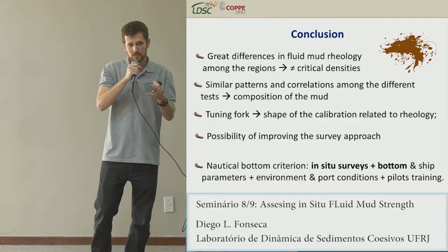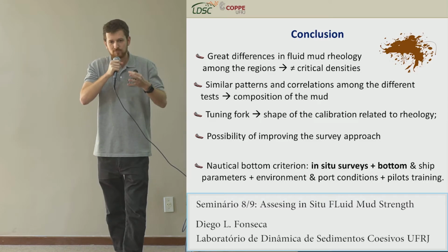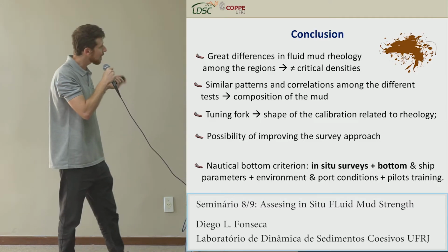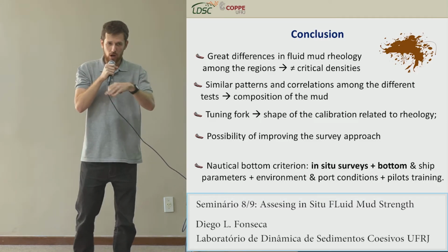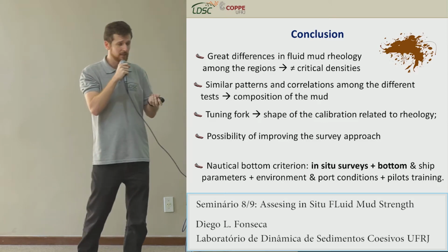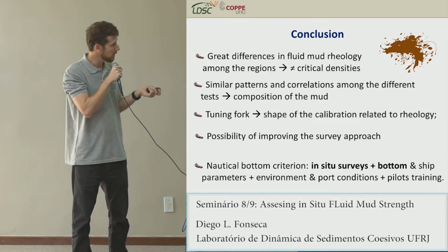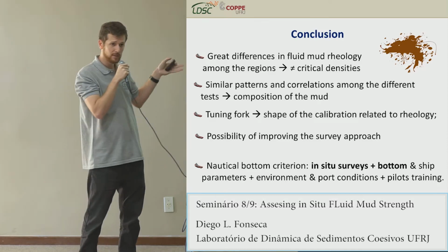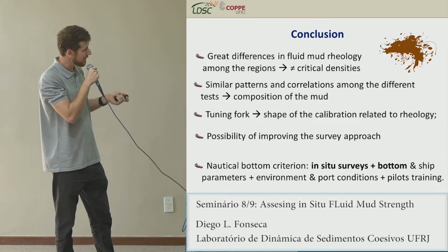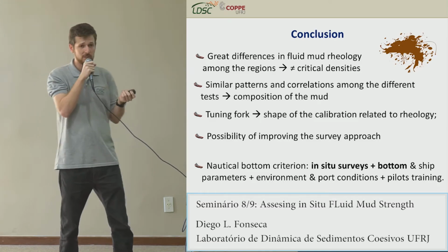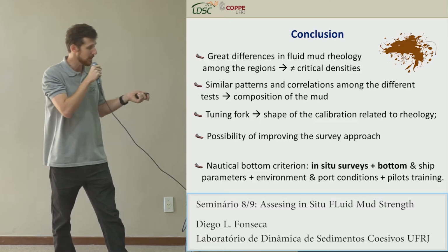But the last message, I can say the most important, is that this nautical bottom criterion that all of us have been talking about depends on in situ surveys, of course, and bottom parameters, as we showed here, but it also depends on ship parameters, environmental conditions, port conditions, and pilot training.